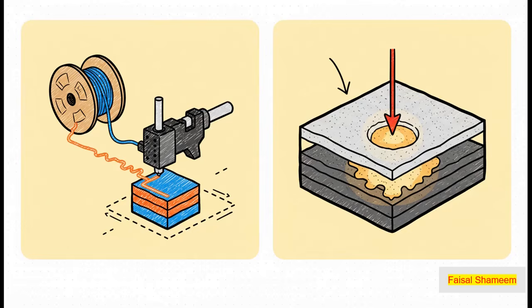It uses a heated nozzle to draw each layer with melted plastic filament, almost like a really precise, robotic hot glue gun. But then, on the other hand, you have a powder bed fusion process, like SLS, which uses a high-powered laser to selectively melt and fuse tiny particles of plastic or metal powder together in a big bed, one little cross-section at a time. It is pretty sci-fi when you actually see it in action.